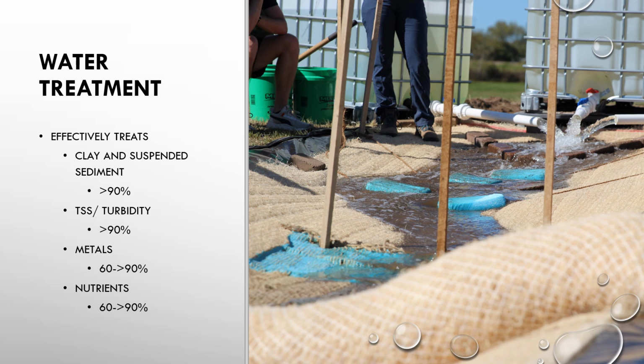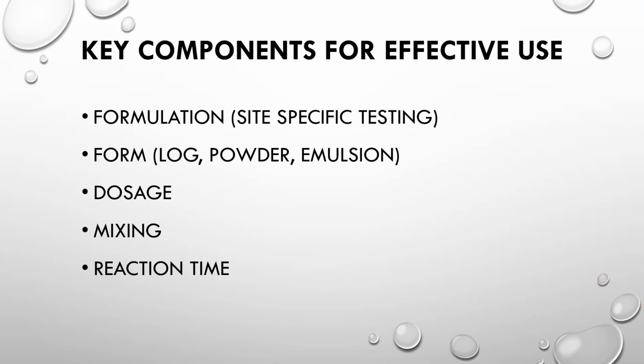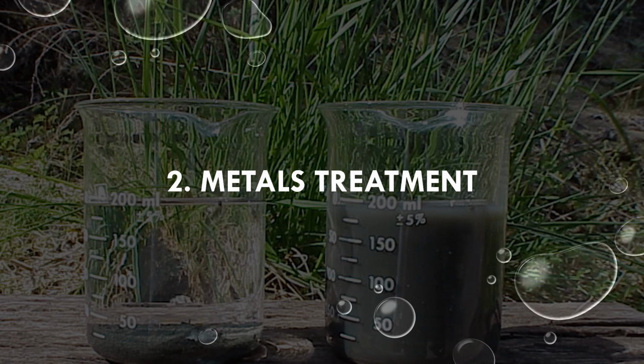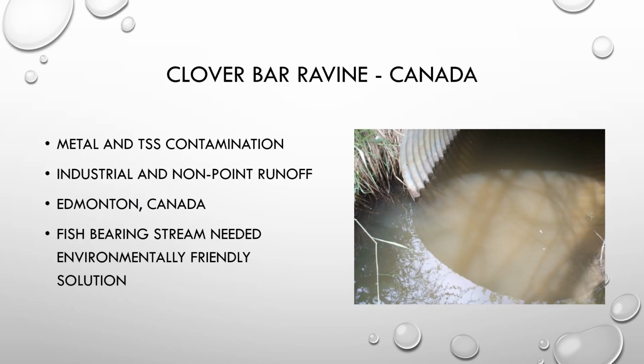We can also handle quite a bit of phosphorus. Depending on whether it's particulate or dissolved, we can often remove around 60 to 70% of total phosphorus as well. So with that, we've gone through, again, those flocculant fundamentals. They're still going to come into play no matter what type of particulate we're trying to remove. We still have to get those flocculant fundamentals, and that's very true for metal treatment.